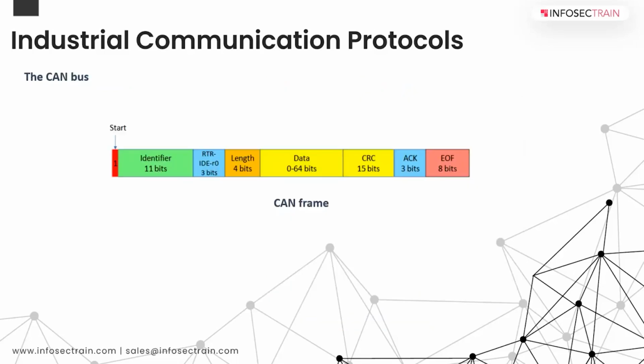And before we go on to the next topic, I wanted to also talk about CAN, which is predominantly used in the automotive sector. CAN stands for Controller Area Network. This was originally developed by Bosch, and it has become its own standard. Actually, there is a specific ISO standard that describes the format and so on. It partially defines the services for layer 1 and layer 2 of the OSI model.